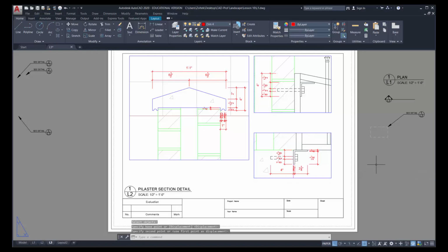Good. So then I'm going to move my lower title reference up below that drawing. Now each one of these has a box, so I can leave the viewports on if I want and use that as part of the box, or what I can do is draw a box over top of it. Now, why is that significant? When you're using boxes to refer to drawings, these title bubbles should be positioned in more or less the exact same place, so it looks very consistent.